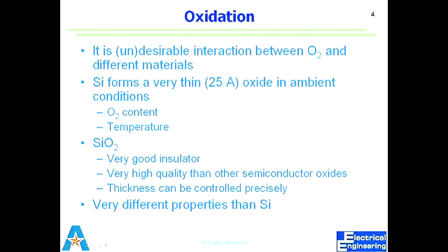It protects the silicon surface, right? So if I leave it for a longer period, I want some oxide to be there, so the silicon beneath doesn't get contaminated. And contamination is again those three things: particles, films, and metallic ions that can change the electrical behavior of the semiconductor.